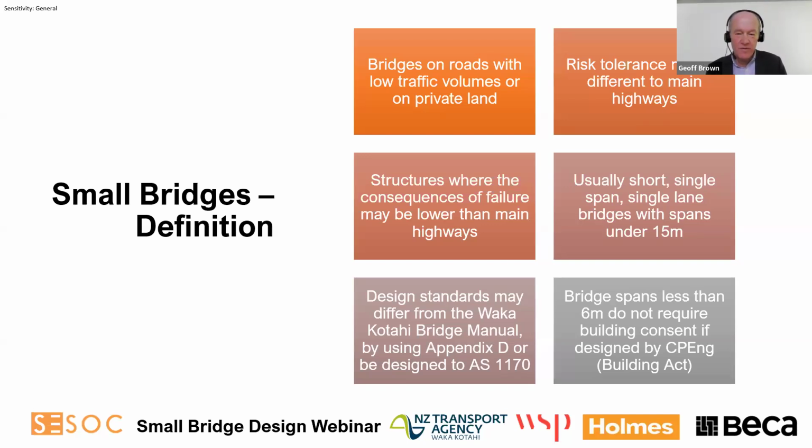They're usually short, single span, sometimes single lane bridges with spans generally under 15 meters. The design standards may vary from the Waka Kotahi Bridge Manual, by using either Appendix D to the manual or by designing to AS 1170 and other material codes. And it's worth noting that bridge spans less than 6 meters do not require building consent if designed by a chartered professional engineer.